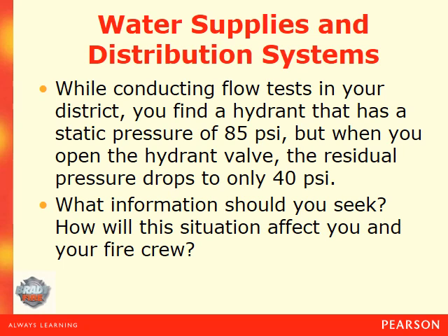So what they're trying to point out here is 40 pounds per square inch is not a lot of pressure on a hydrant that's left, meaning you can't flow a whole lot of water. Now, things to keep in mind: is there a problem with the pumping system? Is there a problem in terms of the amount of water available in the system? Or is this during some sort of peak water usage time? Essentially, everyone's home, they're taking showers, washing their clothes, and flushing their toilet all at the same time.